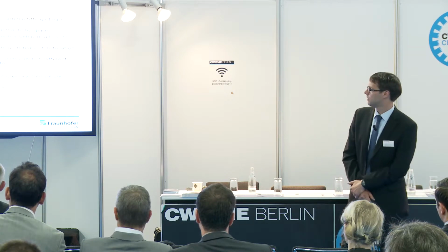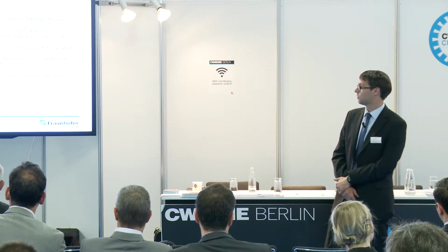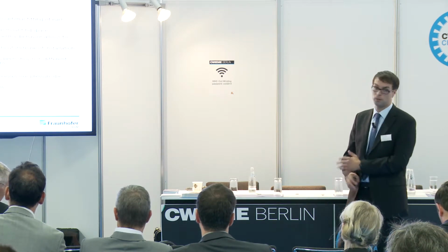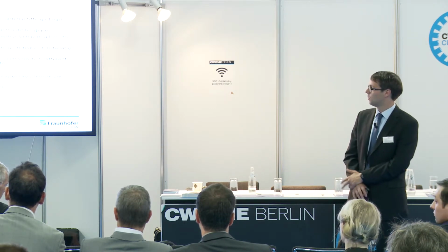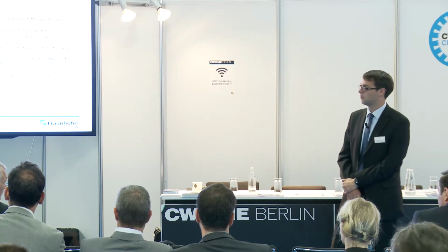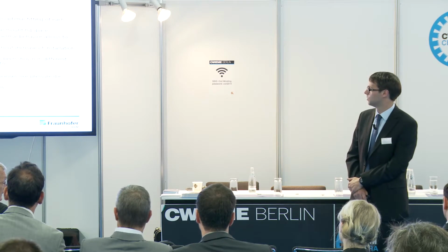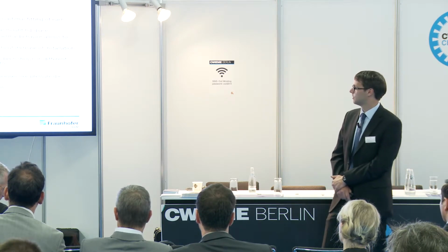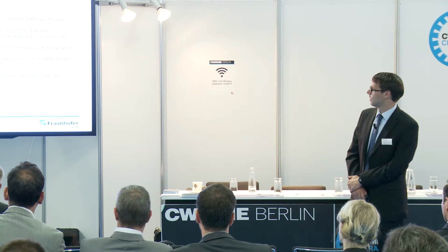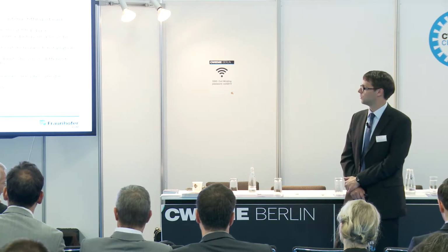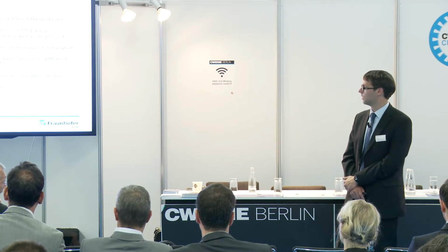As a conclusion, the cast coil process offers high slot filling factors up to 90% due to the optimal fitting in the machine. We can reduce the bending radius, so we can realize no bending radius to better utilize the lamination stack. And furthermore, we have a good thermal behavior to double the current density per slot area.